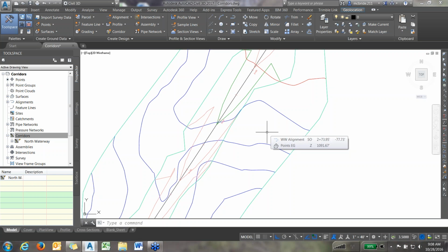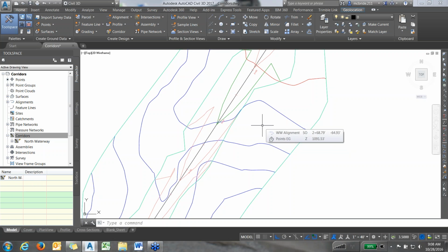So it would basically, if you did the same survey you did at the very beginning, be what it would look like once you have them merged, okay? And this is a step-by-step process that I don't think is in your notes. I thought we did it in the surfaces one, but then I realized we took LiDAR out, so we didn't do it. But just real quickly, I have to copy the existing ground surface, and I can't just select it and copy to the clipboard. I have to go up to the ribbon and select copy.